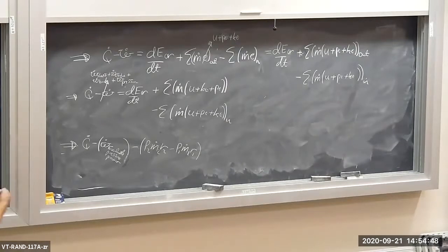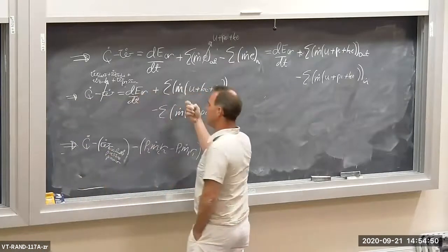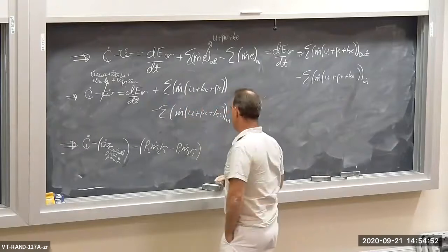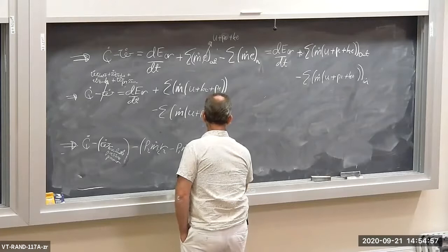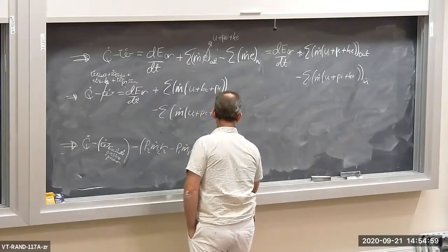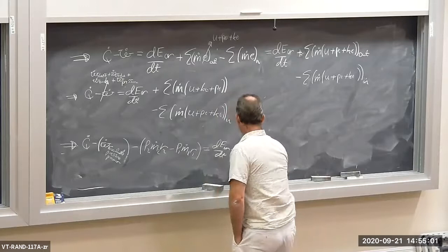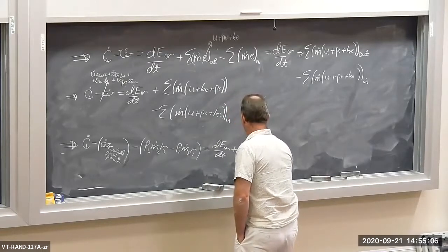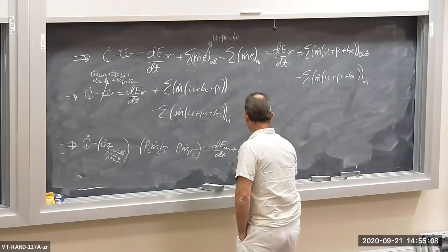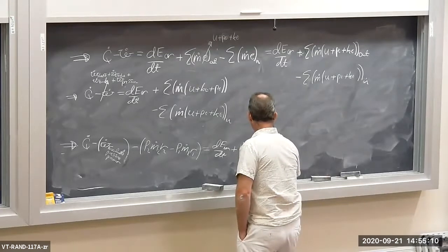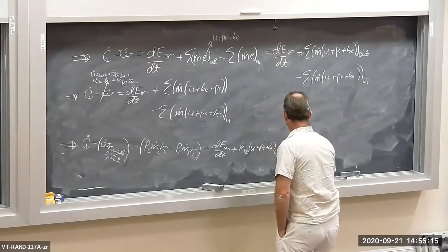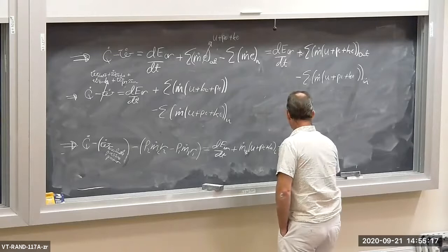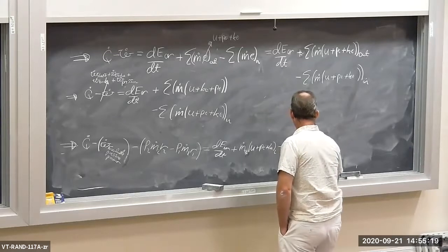By the way, in our channel problem, we only have one inlet and one outlet. So I'm going to write dECV dt, and then I have one inlet and one outlet. So M dot 2, that's my outlet, U plus PE plus KE2, minus M dot 1, that's my inlet, U plus PE plus KE1.